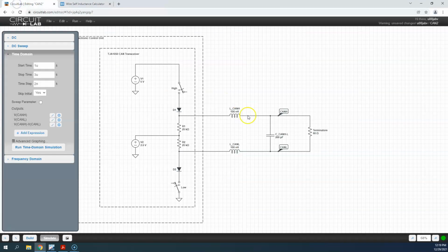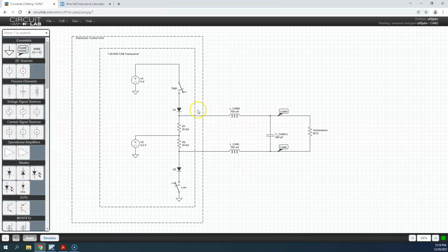So if I were to take this and put it into my simulated circuit that I have here, the data link, this is the CAN transceiver that we showed from the last two previous episodes. I'm going to have the two switches and, as best I can, model a 5 meter long piece of J1939-11 cable. And I have my terminating resistors here. I've modeled both of those together.